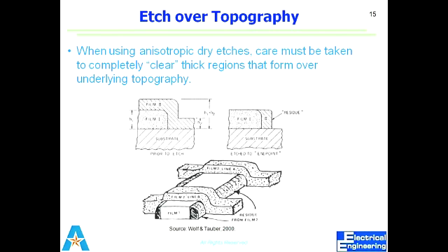It's actually like this: if there was a residue and after that I deposited the second film, this was the first film, so you can see that in this part the thickness is the same as in this part. If I have exposed my wafer in dry etching, or even in wet chemical etching, but because it's directional I'll assume dry etching, then by measuring the thickness of film 2, this much thickness will be removed, but this is left. So that's why I always prefer to go for over etching, so that I make sure there is no residue left.